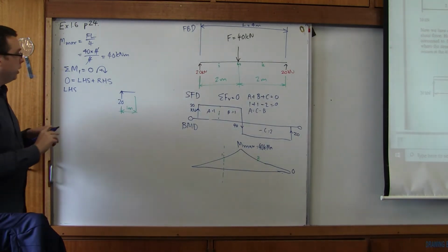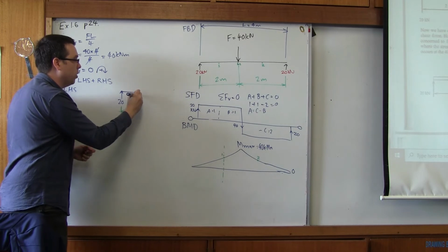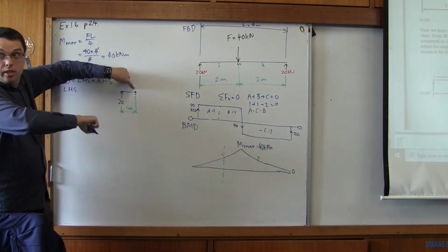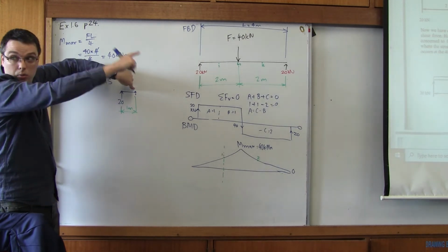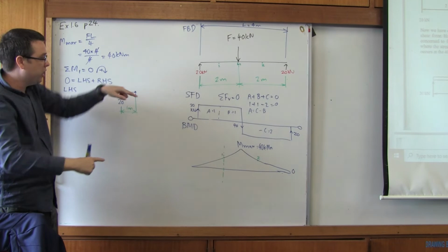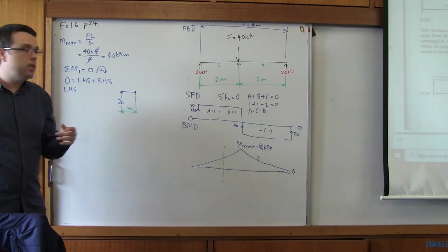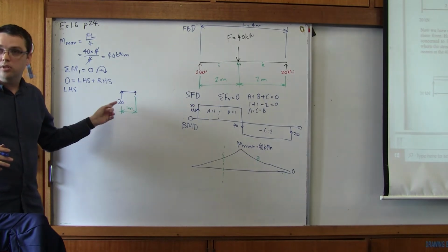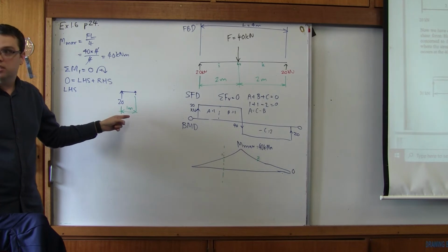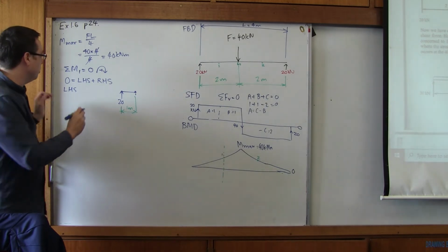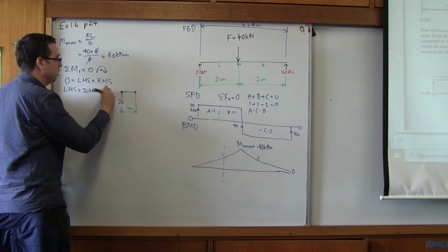Okay, so its force, if we're putting our pin at location 1, and we're going to rotate it, which way are we going to go? Clockwise. What's its value? Positive. The magnitude is force times perpendicular distance, which is 20. Exactly right. 20 kilonewton meters clockwise.